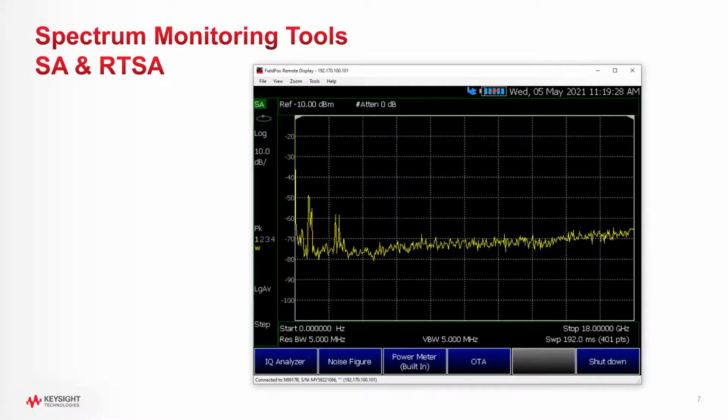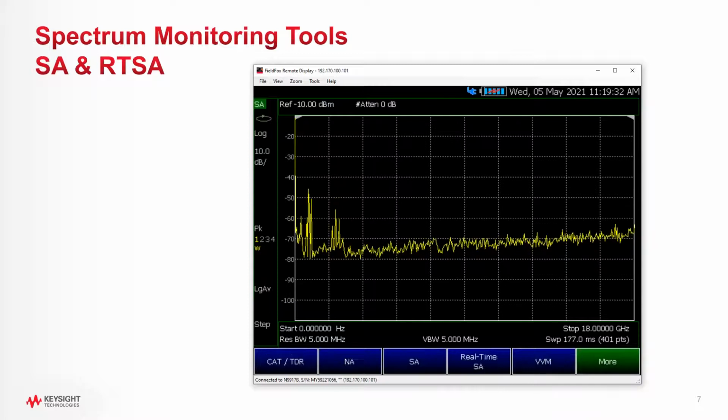So that's the way the FieldFox starts, with the different modes you've got enabled. If you buy a base cable analyzer, what we call the combo box, with no modes activated, it'll just say CAT, it'll test cables and antennas, that'll be its base function. All the rest of the stuff you turn on. We also make models that start out as spectrum analyzers if you don't need to do network analysis or cable test. But we're going to use the spectrum analyzer today, which is what we're on.